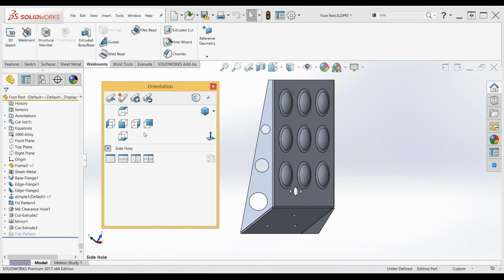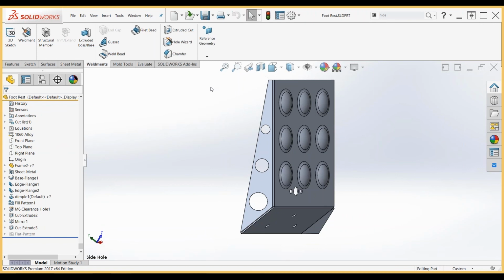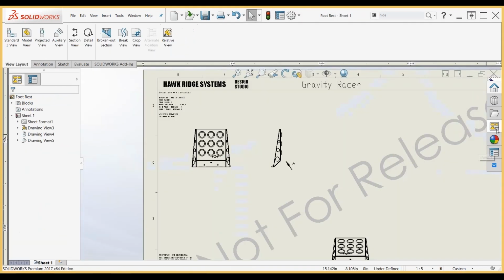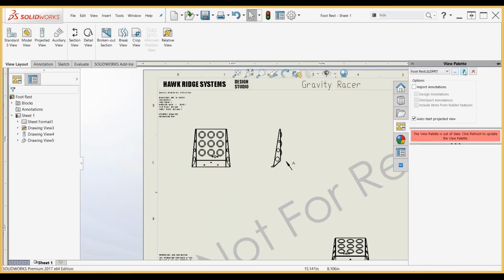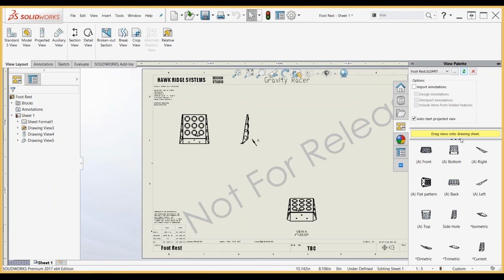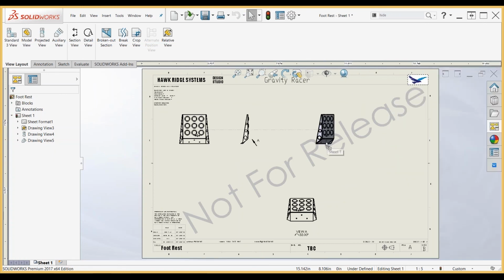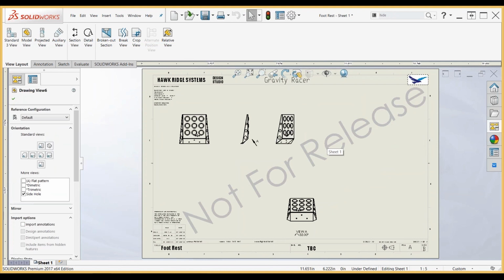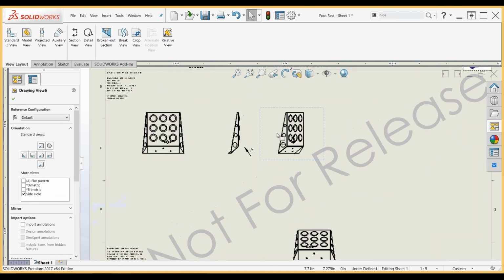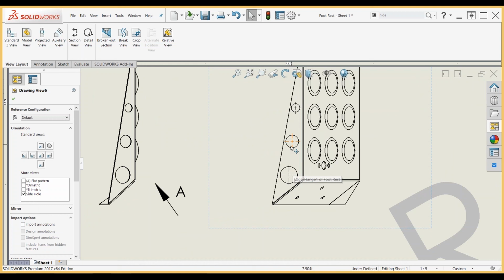Super cool. So new in 2017 are these jagged outlines. Without that, that slot is really symmetric, and it's hard to tell, okay, is that part of this dimple feature? What is that? Is that model geometry? Is that my cut boundary? With this jagged outline, you can ensure that, yep, that is where it's been cut. That is not part of my model geometry. And you can play around with the intensity of it. You can make it kind of loose like that, or pull it in a little finer. Whatever you want, it just shows that that is the cut boundary and not actual model geometry.